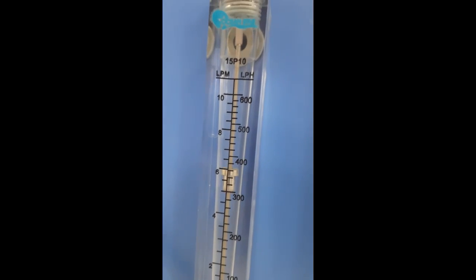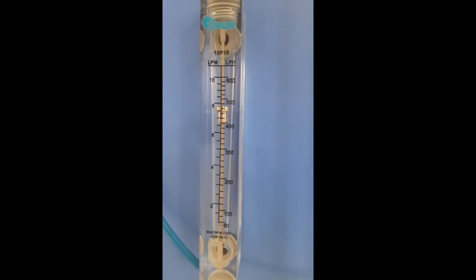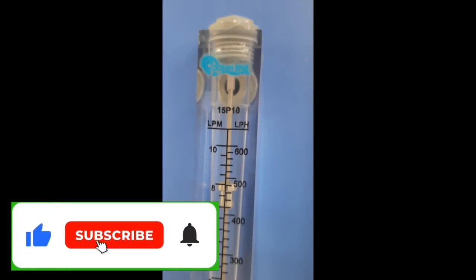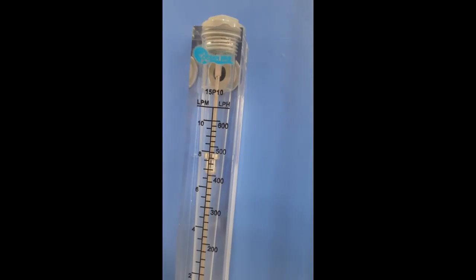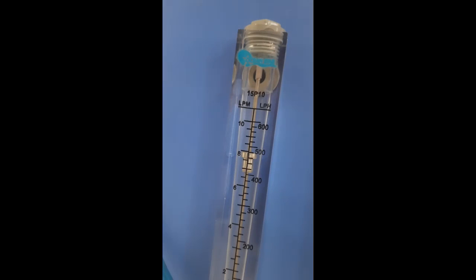Say for example, right now we kept the valve position such that we have the LPM at 300, and now we are increasing it by opening the valve. It is increasing to 500 LPM. So we can again reduce it by closing the valve. Again the float position, you can see it is moving down from 8 LPM to down.